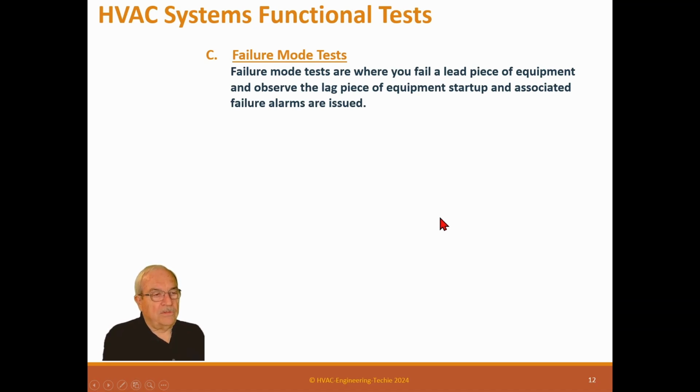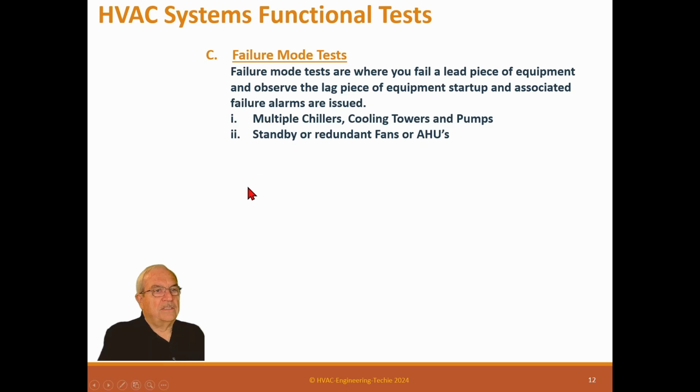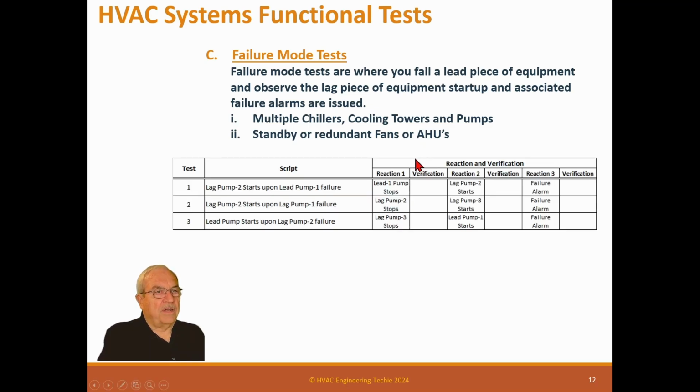Now, failure mode tests are also very important. Failure mode tests are where you fail a lead piece of equipment and observe the lag piece of equipment startup and associated failure alarms are issued. So manipulate chillers, cooling towers, and pumps. Standby are redundant fans or air handlers.